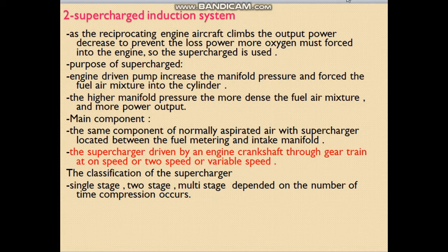Supercharged induction system. As the reciprocating engine aircraft climbs, the output power decreases. To prevent the loss of power, more oxygen must be forced into the engine, so a supercharger is used. Purpose of the supercharger, an engine-driven pump: increase the manifold pressure and force the fuel-air mixture into the cylinder. The higher the manifold pressure, the denser the fuel-air mixture and the more power output.